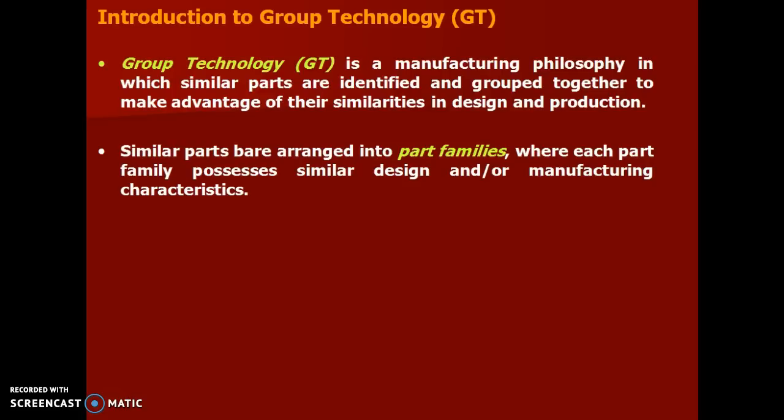Group technology is a manufacturing philosophy in which similar parts are identified and grouped together to take advantage of the similarities in design and production. Here, similar parts are arranged into part families where each part family possesses similar design or manufacturing characteristics.